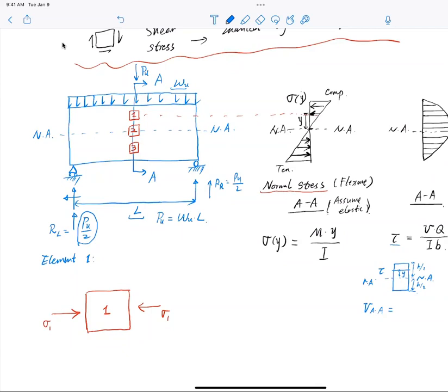If you think of a shear diagram, let's overlay it on top of this. At the left I have this force here, so the shear has to balance this force, so it's constant. But now, as I have these distributed loads, I'm going down to a certain value here, and what is that value? Zero. Yeah, I remember now. Zero. It is zero. So if that's zero here, I flip back here, and then to the PU value here. Thank you, Alex, again.